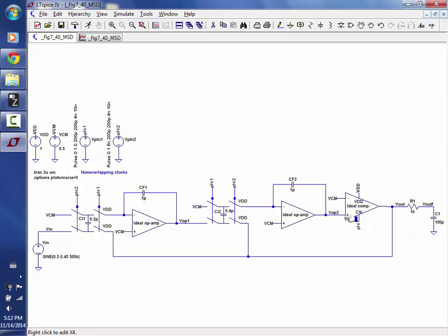We want it to be very decisive that, hey, I need to remove a cup of water here, and you only get that when you get big swings here. So keep that in mind. And you get big swings by using small capacitors, which also pushes out the bandwidth of your integrator and makes it easier to drive. Does everybody follow that?